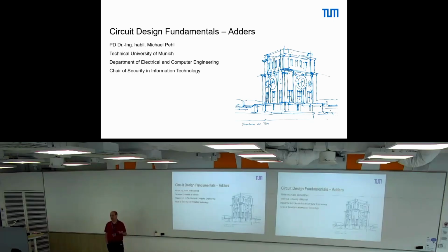Another drawback of carry look ahead when compared to RCA? So we have fan in, fan out. It's bigger, larger area. So carry look ahead requires more area because we do all this carry computation in parallel. Then what did we have next? We had the PPAs, the parallel prefix adders.